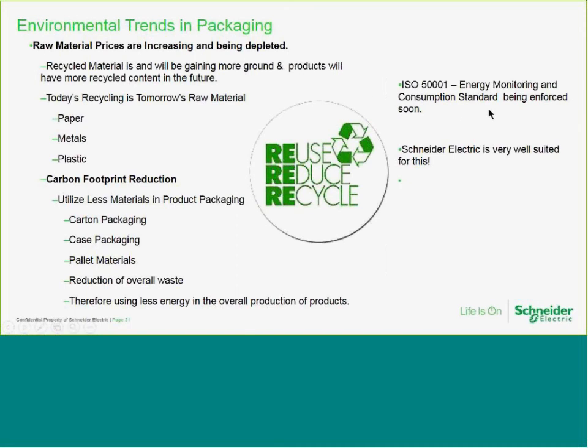ISO 50001. I don't know if any of you have heard about this. Maybe 10 or 15% of people that I talk to are familiar with this, but this is a new regulation coming out in the near future where they want end users to know the energy consumption of their machinery. Within our pack drive control, we can tell you how much current and power is being used by each axis from our centralized control system, but to actually monitor the overall energy of the machine, you might need an energy monitoring device on the input, and Schneider Electric has a variety of options to do that.